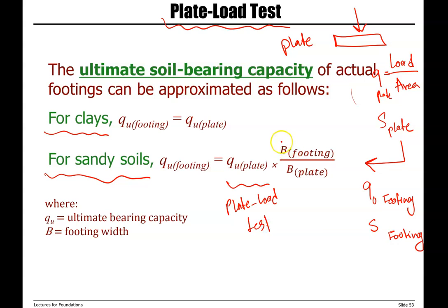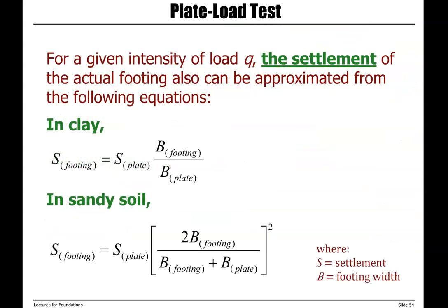times width of footing divided by width of plate. This is width of plate. We also know what is width of footing. We can calculate ultimate bearing capacity of footing when we do the plate load test and have the result for ultimate bearing capacity of plate.